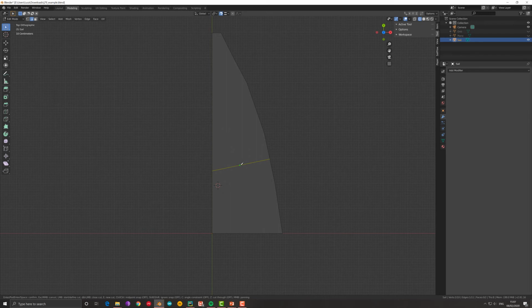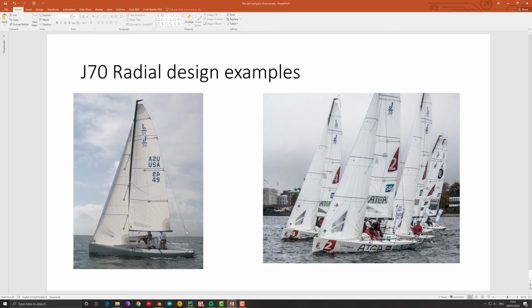Okay, then in the middle of it you have to draw a line to the bottom of the sail, but the best thing to do is to select the edge and press subdivide, so you have two exact same length segments. Okay, then you press K again and you have the knife and you go to the base of the sail, you click, you press enter and you have it divided in two. So now let's do the left part of it. You see it's a number of arrows.